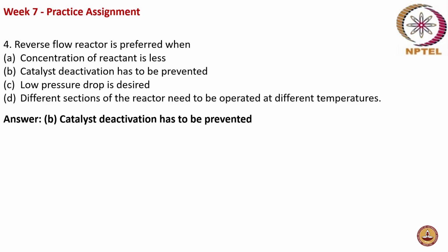So the reactant passes through the inner diameter and then through the outer diameter, by which the lean reactant concentration can be supported, because this will preheat the fluid, which is necessary to increase the reaction rate of the reaction. This is also called, it is nothing but, the autothermal operation.